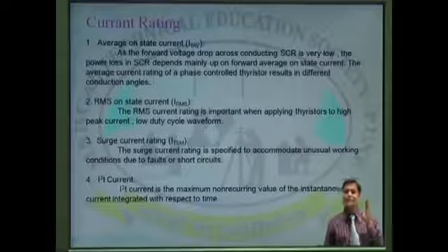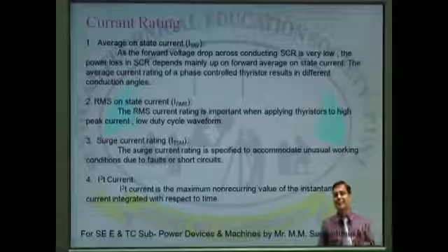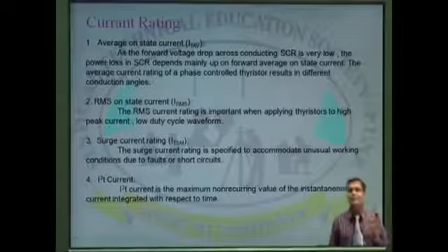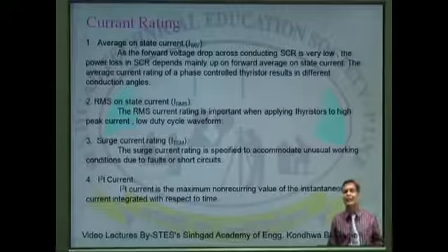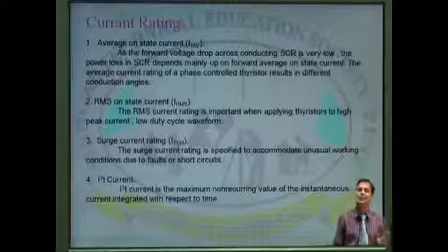Then the third rating, especially, is taken into consideration for abnormalities in the circuit, such as short circuit or fault in the circuitry. Means if a short circuit happens, then excessive current may flow across the SCR and will damage the SCR.